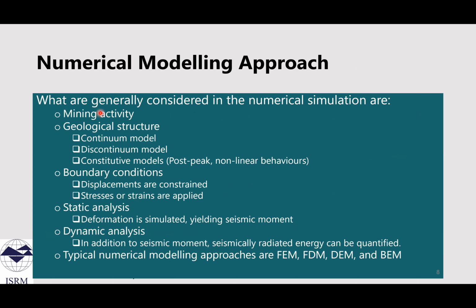In addition, we need to model the geological structures that could cause seismicity. And the geological structures can be modeled with various methods. For example, we can use the ubiquitous joint model to simulate a shear zone, while a thin fault can be modeled with the interface element.